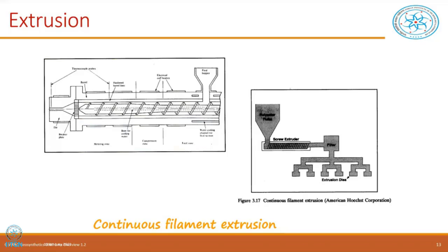And as it is coming down, it is heated definitely. That is, the heating elements are shown here. It is heated continuously, and once it becomes liquid, it is pushed out to what we call a spinneret or extruder. So this is horizontal spinning, you can see that, and here it is vertical. By and large, this is very common. So we find that we get this extrusion.